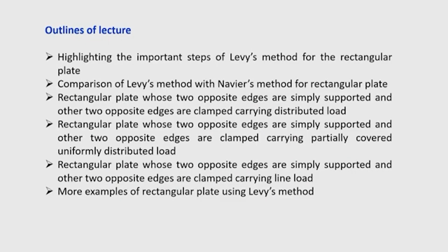So, today's lecture outline will highlight the important steps of Levy's method for rectangular plate, and a comparison of Levy's method with Navier's method for rectangular plate. Then we will illustrate a problem of a rectangular plate whose two opposite edges are simply supported and the other two opposite edges are clamped, and which carries a uniformly distributed load.